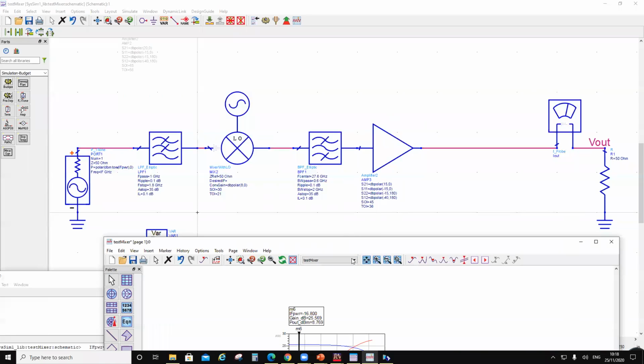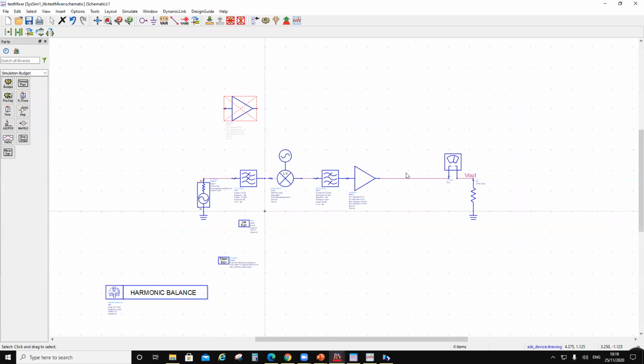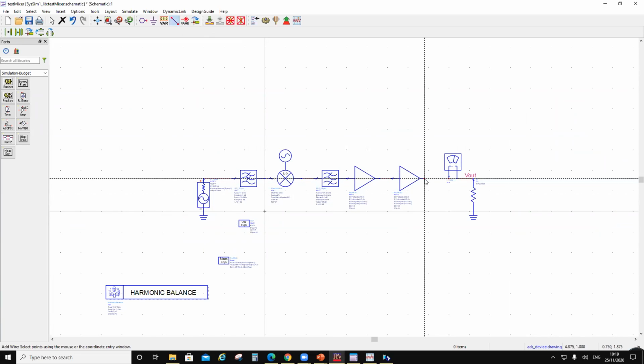Now this is compressing at 25.5, 24.5. Let's see, 24.5. At this point, it is putting out 24 dBm, and then I have the power stage. Somehow that ideal VGA was an issue. I am not sure why it was an issue. I have to figure this out. And then there is a PA here.